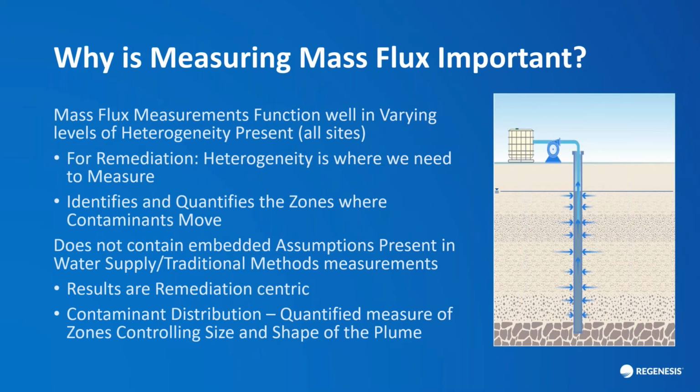So as I mentioned previously, when we use water supply methods, in this case, in the figure to the right, I'm showing an extraction well. You can see the various levels of contribution during the pumping cycle contributed by various levels or units within the target treatment zone, that being the saturated screened interval. Bulk aquifer measurements like this do not help you determine where mass is and how fast mass is moving.